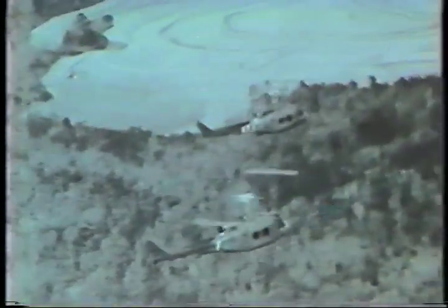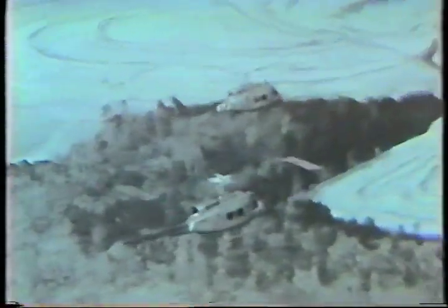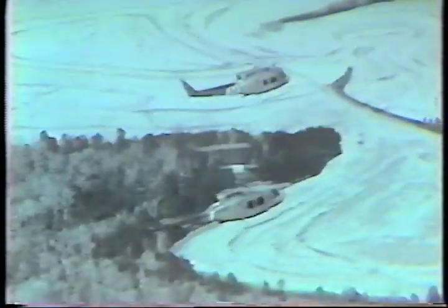After the formation has closed into a staggered trail, the flight leader will announce the time interval between elements and receive an acknowledgement. The first two aircraft will continue on course, and if load and flight conditions permit, they will increase airspeed by 10 knots. The second two aircraft will maintain their airspeed, while the remainder of the formation will decrease their airspeed in pairs until the desired separation is attained.